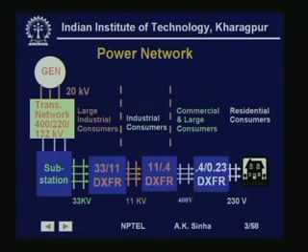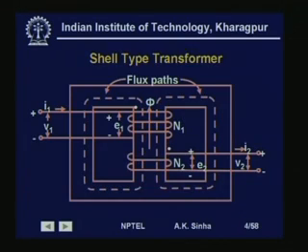So, we have to model these transformers mathematically when we are trying to analyze the transmission system. So, we will now go into the modeling of the transformers. Before we start with the mathematical model, we must understand that there are two kinds of transformers that we use. This depends on the basic construction